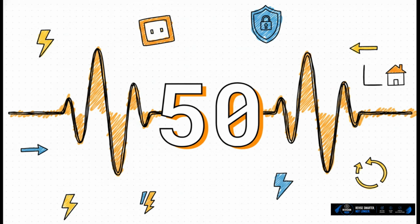On top of that, this alternating current changes direction with a frequency of exactly 50 hertz. That means it completes 50 full cycles every single second. If you remember your equations, specifically time period equals 1 divided by frequency, that means one complete cycle takes just 0.02 seconds. It is incredibly fast. So remember these two golden tickets, 230 volts and 50 hertz.